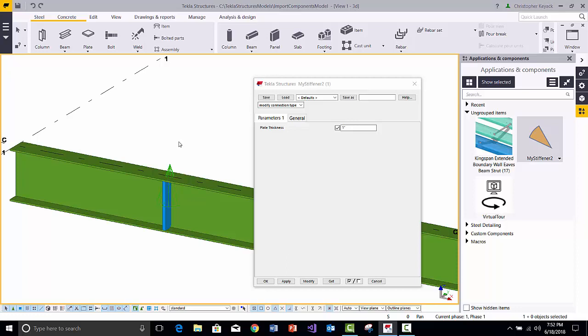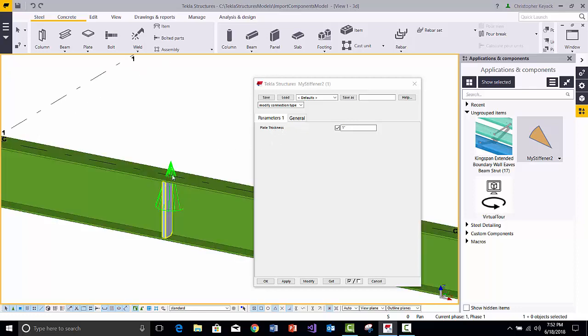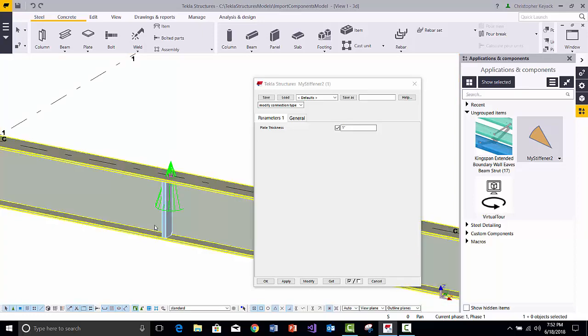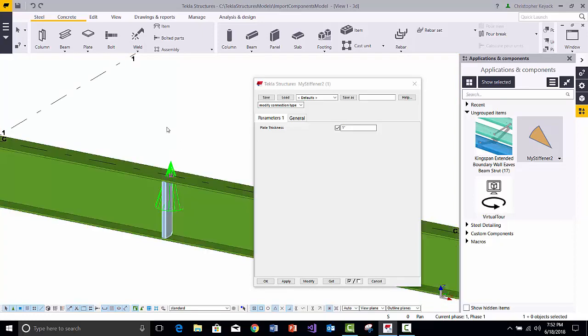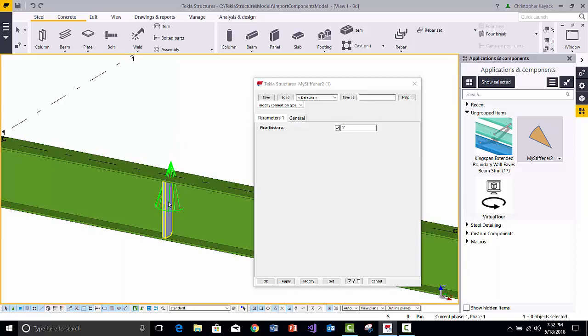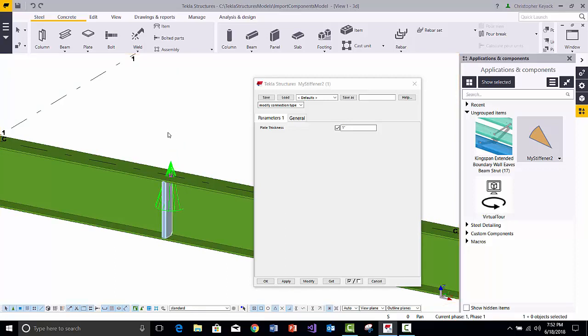Only do the bindings and make parametric value fields that the user enters on the dialog box based on things that are going to change. Otherwise, if there are constant properties or things that are the same across the entire job, just leave those hard-coded as they are inside of the component. Only do the bindings or the value fields or the parameters of things that need to be parametric.